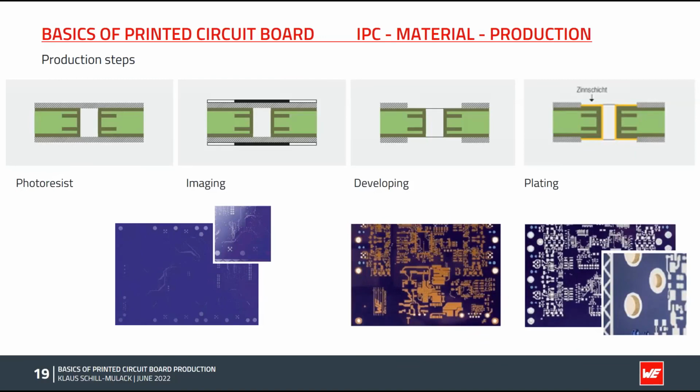In a further photo process, the layout of the outer layers is transferred to the PCB. The process chain is nearly similar to the process of the inner layers, except that the resist is now used to partially build up copper. As you remember, in the first photo process, the resist is to protect the copper in the etching process. So now here, all areas outside the layout remain covered by resist, and the PCB layout is defined in the resist.